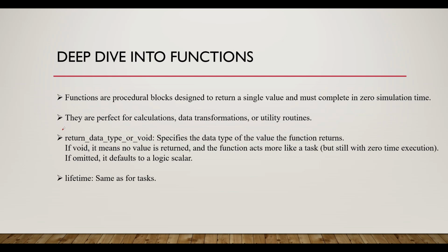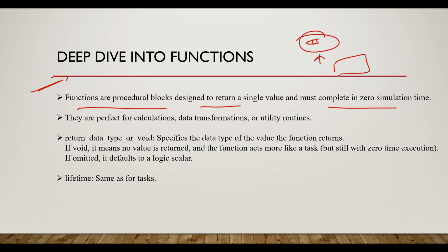Now let's deep dive into the function. A function is also a procedural block designed to return a single value. Like our task, your function is a procedural block mainly designed to return a single value and must complete in zero simulation time. Whereas our tasks can take some delay, functions are not allowed any kind of delay. I hope it is clear to you.